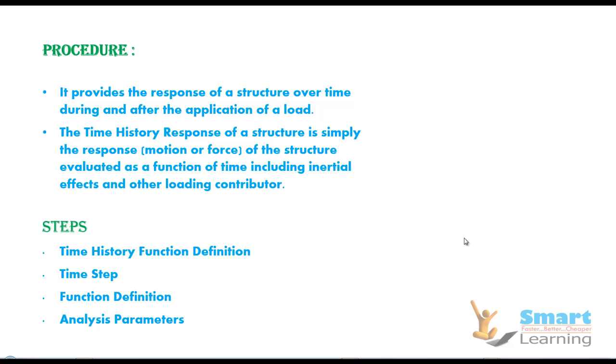The time history response of a structure is simply the response or the motion or the force which you apply to your structure and is being evaluated, which is a function of time, including your inertia effect and other loading contributors. So when you talk about the steps, you can have the time history function definition, the time steps, and the analysis parameters.